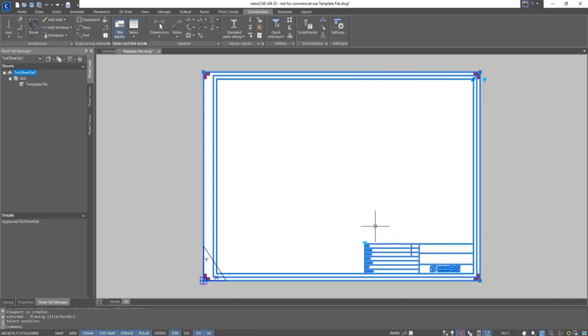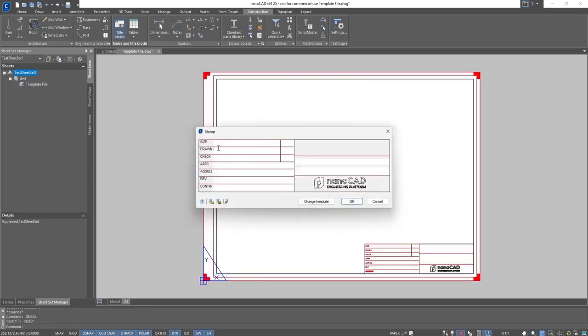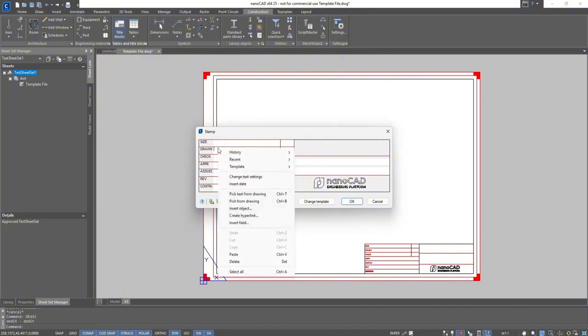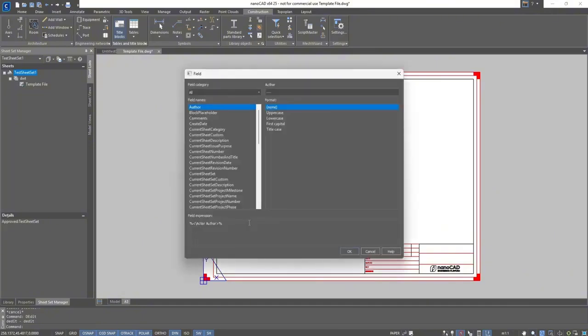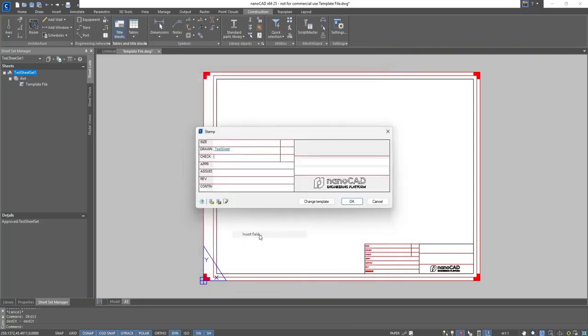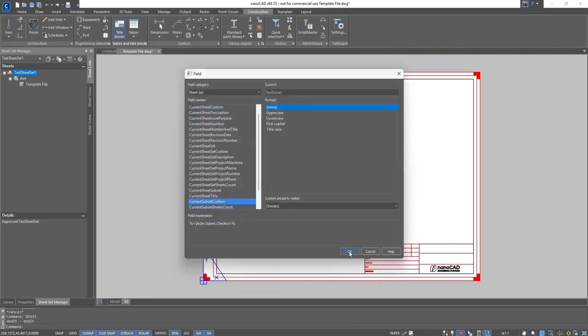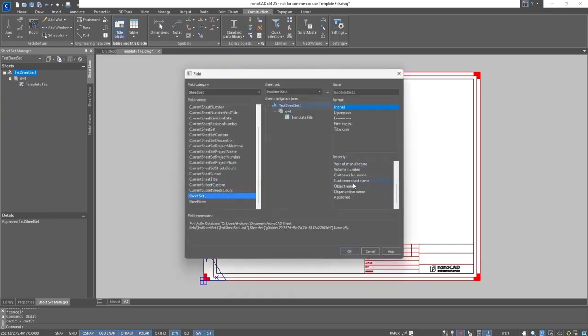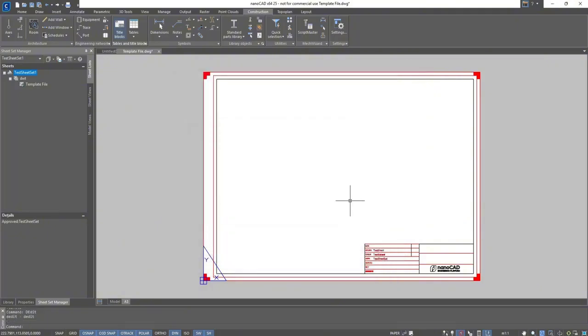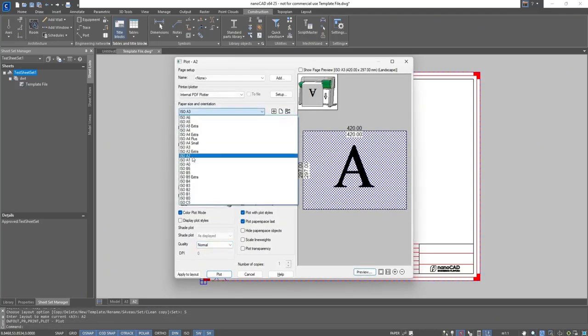Double-click on the stamp, going to its settings, and then right-click on the field to which we will add properties. Select the Insert Field option. In the Field category, Field Set, Sheet Set. For Group and Sheet, the created properties are stored in names that have custom in their name. And for Sheet Set in the field of the same name in the property window. When creating new layouts, don't be worried that some fields are shown with a hash symbol. This will work correctly in the future.